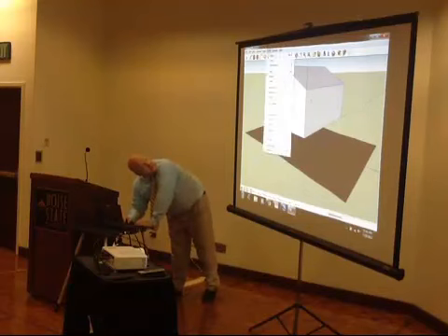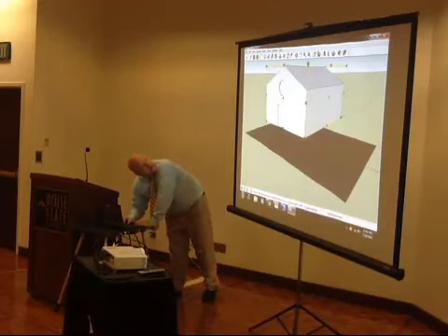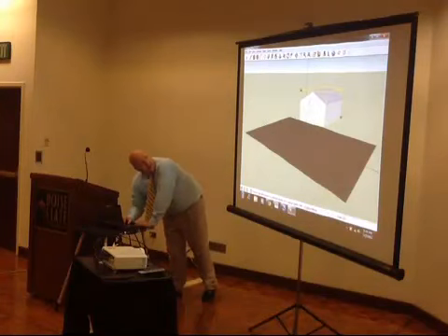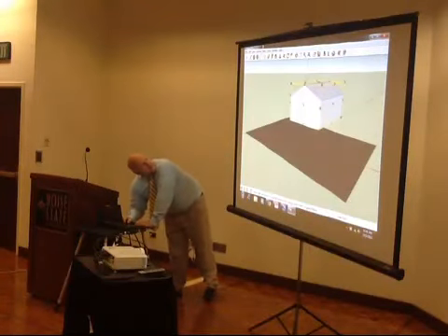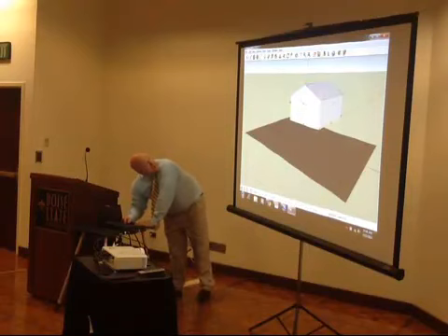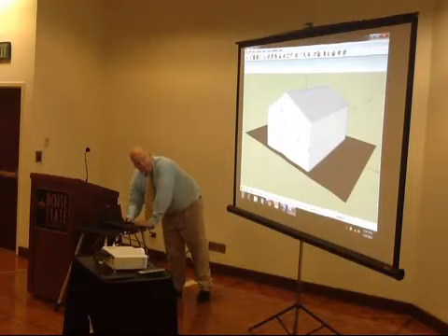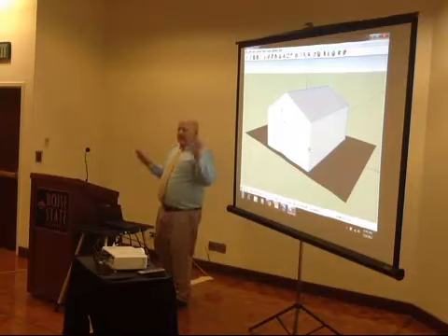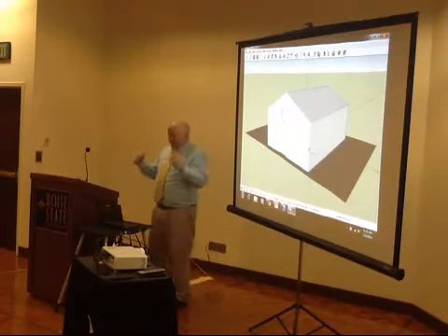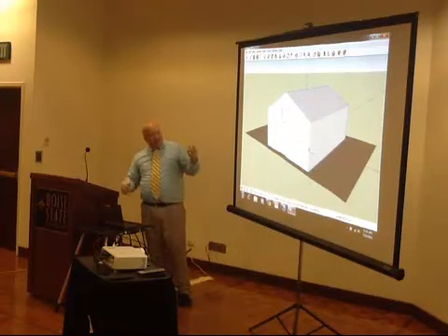If you go to the Tools menu and say Scale, then you can drag this down and make it into a more viable space. With it still selected, if I use the Move tool, I can move it over on top of my space. Now this is not how you would do things, but in the interest of time, I'm just popping it into this space.